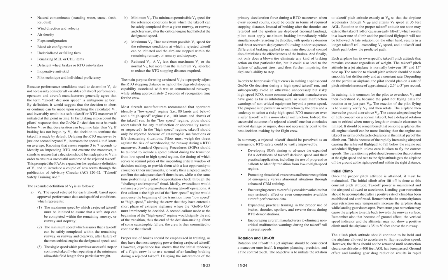Proper use of brakes should be emphasized in training, as they have the most stopping power during a rejected takeoff. However, experience has shown that the initial tendency of a flight crew is to use normal after landing braking during a rejected takeoff. Delaying the intervention of the primary deceleration force during a RTO maneuver, when every second counts, could be costly in terms of required stopping distance.